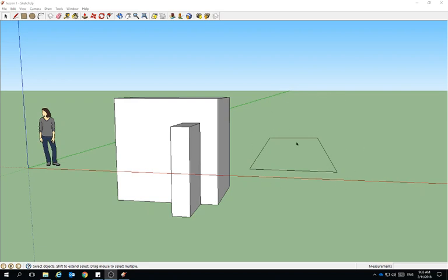To point out that it's not filled with a grey colour is important, because it means that there's something wrong with this shape. So when you're trying to create a flat shape of any sort of orientation, any size, any amount of sides on it, SketchUp will try to fill it with a solid grey or white colour, to show you that it's recognised it as being a solid sealed shape. So that's our first little cue here that there's something wrong with this one.